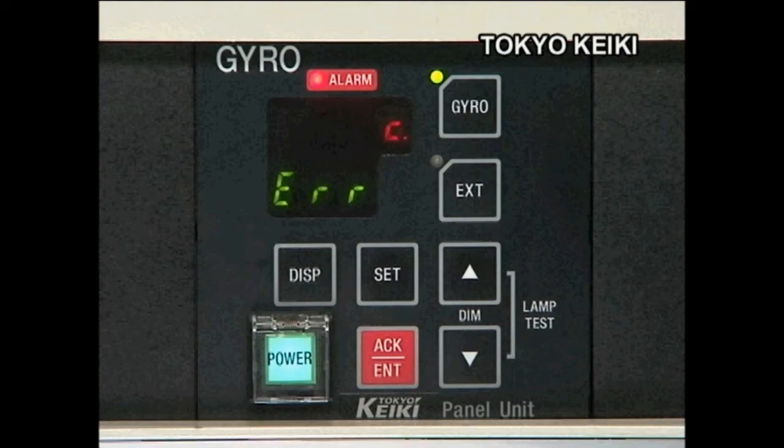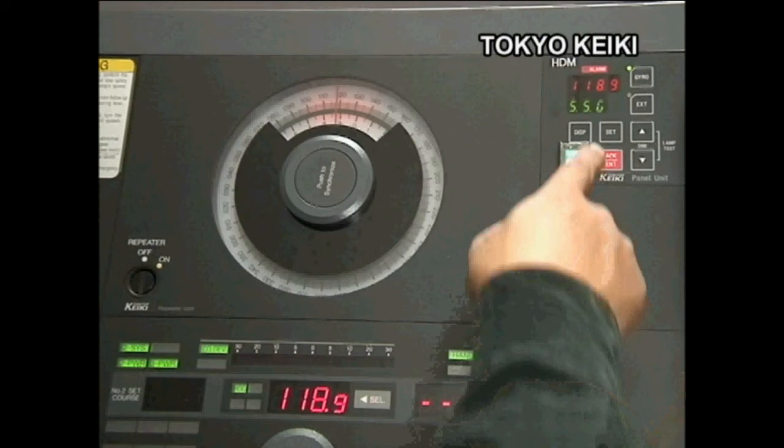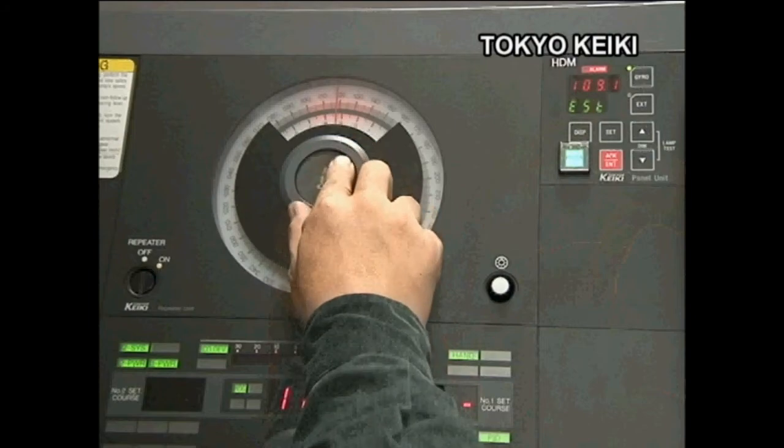For Tokyo Keiki's system, switch off the repeater power supply. Switch the azimuth input signal from gyro compass to magnetic compass using the switch provided on the steering stand. Next, align the azimuth of the compass card of the steering stand to that of the magnetic compass.